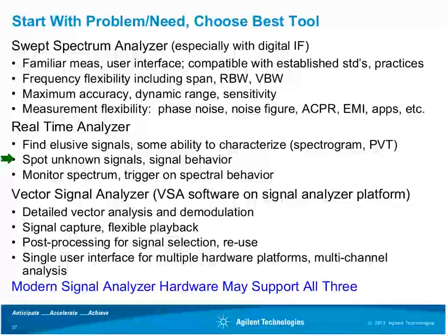But as I've discussed here today, the vector signal analyzer, software or hardware, is an excellent complement, with the real-time analyzer being a good tool for signal discovery, and the vector signal analyzer being a tool for detailed signal analysis, including things like time domain and demodulation behavior, whether analog or digital, single or multiple channels, and then using things like signal capture and playback. Basically, find the signal you want, press the button to capture it, and then press the play button.